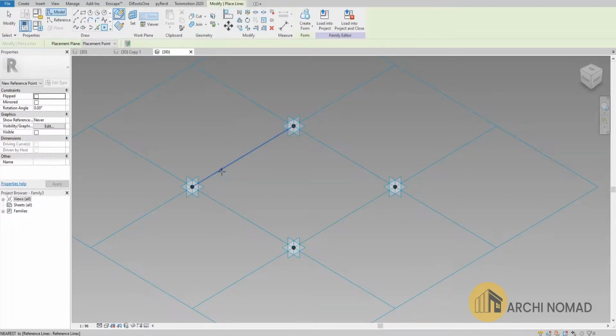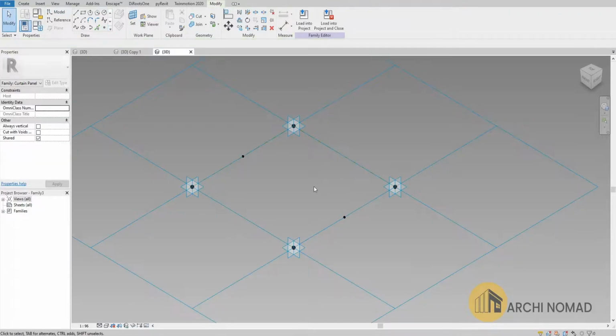And then you just have to go somewhere in the middle. And I'll try to use copy method. So I'll just create few points, then I will create a copy for all this area. So I'll just click one here and click one here, hit escape to exit this command.